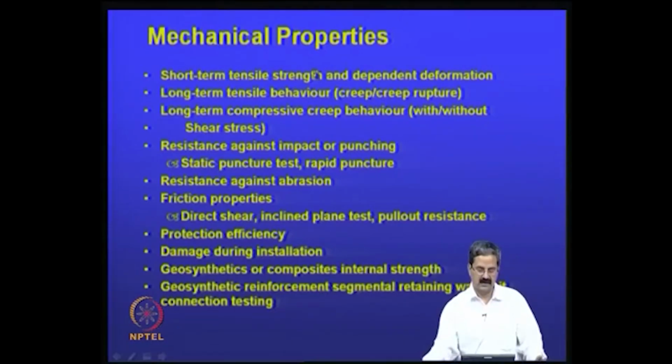Mechanical properties are what we need in most of the applications. So, we are looking at short term tensile strength and its corresponding deformation, and long term tensile behavior, meaning the time dependency: you wait for different periods of time and find out what the change in tensile strength is. Then long term compressive creep with and without shear stress. In fact, we do this in soil mechanics: we apply load and at the same stress level we allow it to settle for a longer time, which we call creep behavior.